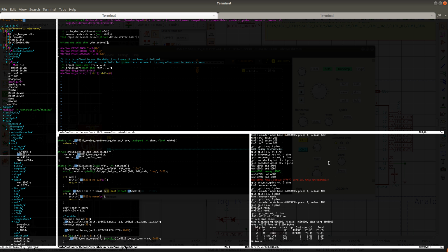It could be related to some I2C device not really behaving well. Maybe I would need to reset the I2C bus manually, by just toggling the GPIO pins manually and resetting every single device, if this problem persists. Okay, so now I have the other one.